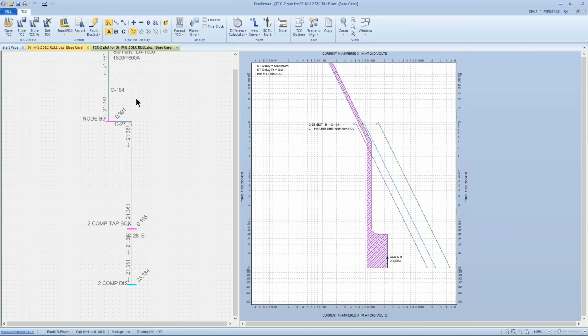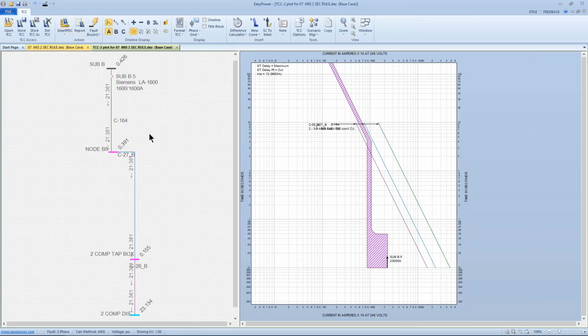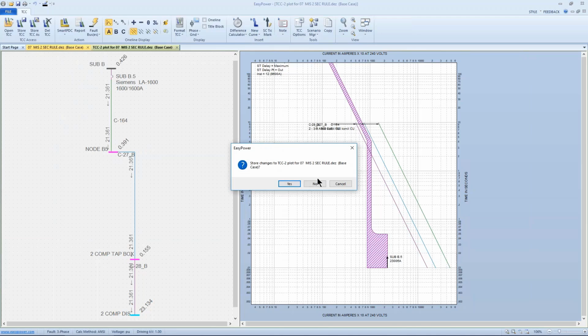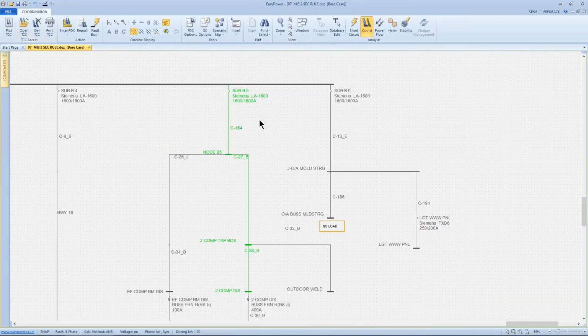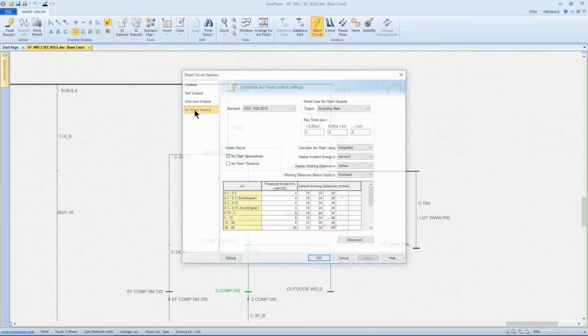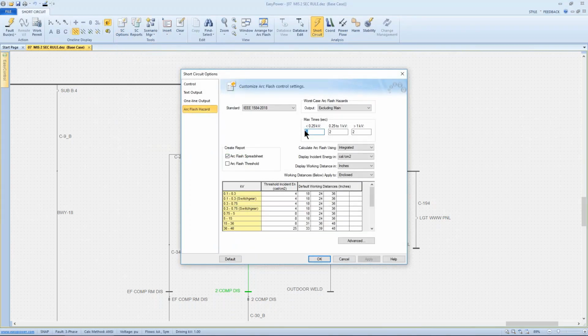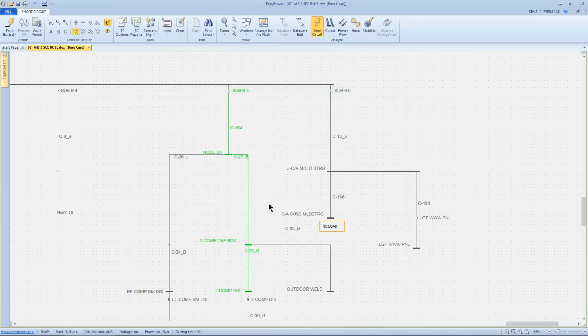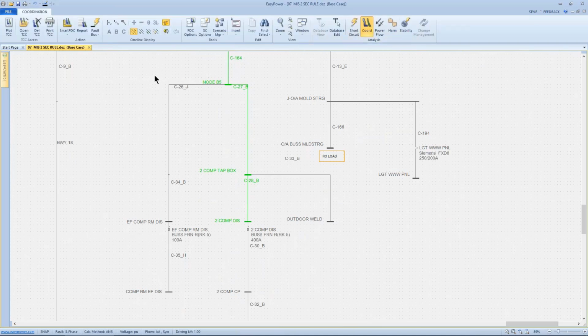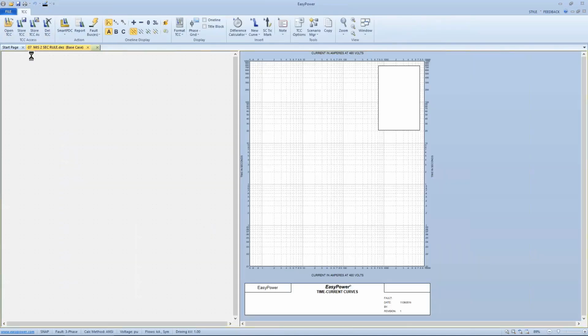Let's try this one more time. Actually, I want to go back. What the tool is telling me is that this is not the limiting device, and we're still stuck on our 2 seconds. So sorry about that. I have to go back and look at my 2-second option relief, take that relief away, and now go back to our coordination and plot the TCC.